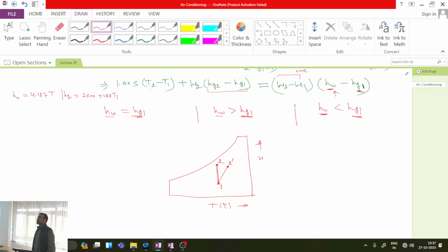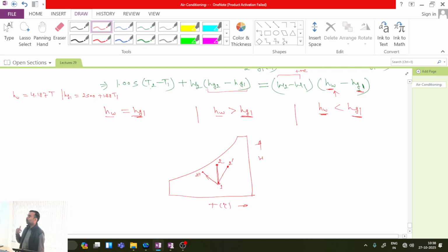So this is the process of evaporative cooling. Okay, so in this process what will happen? In this process temperature will decrease because enthalpy of moist air is being utilized to achieve evaporation of liquid droplets which are added into the medium.